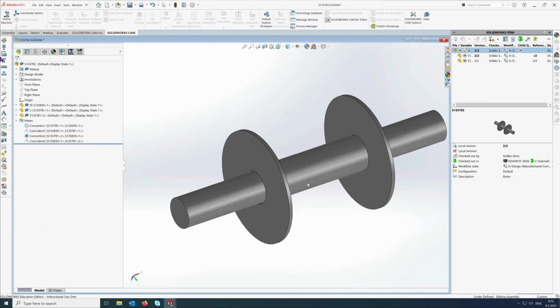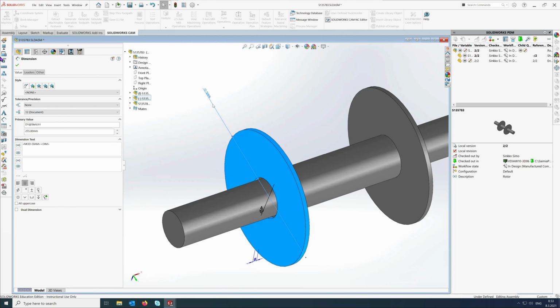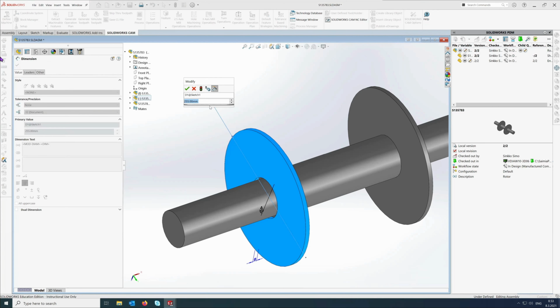And now with this part, you can see the thing that I told you, that this main diameter is more than what we would need at the end. So we would need 250, but now we have 255. This might be a little bit too much. I think 2 or 3 millimeters would be enough. So maybe I can change this now. I will remove 2 millimeters from here.